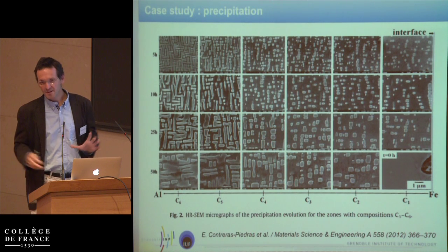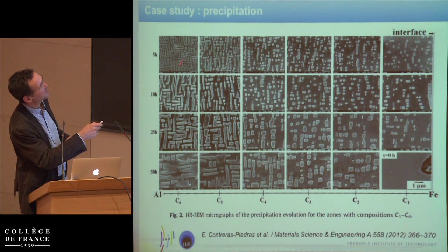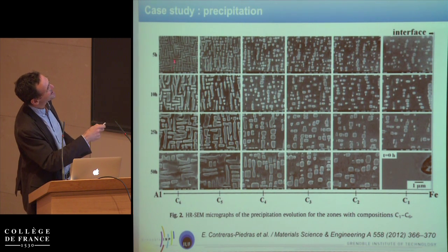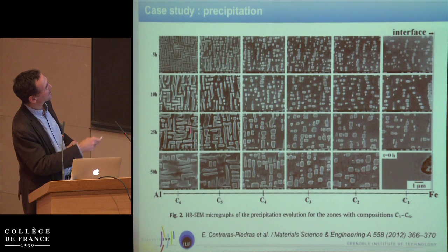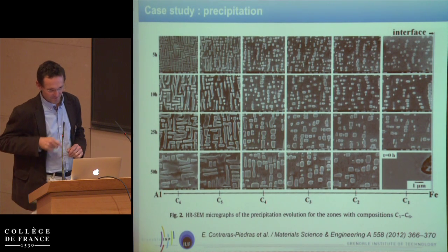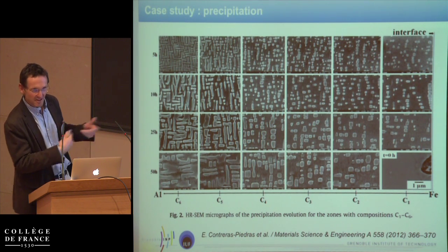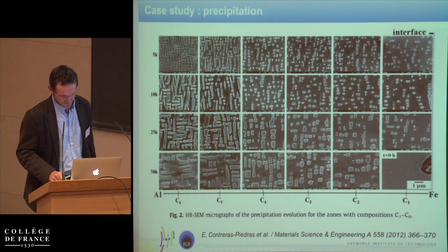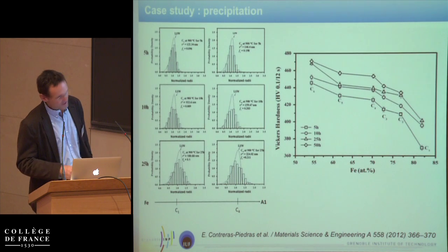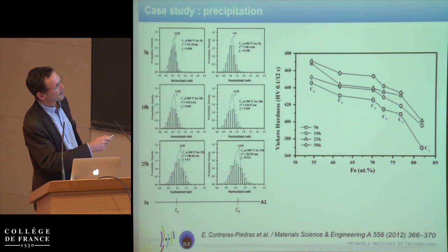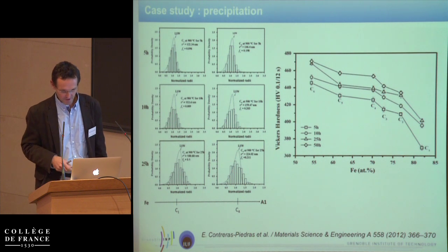And then you can map very beautifully the kind of microstructures. We could say maybe they're architecture, but this is not my point here. And see that for different times and compositions, you get a deep percolation and you get some alignments and so on. And then you can select, of course, some compositions and get into more detail about how the compositions suit your requirements. And then you can even quantify these microstructures to get really the evolution for different aging times of the precipitate microstructures.